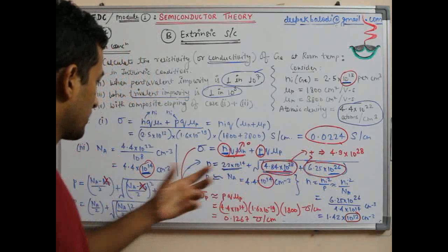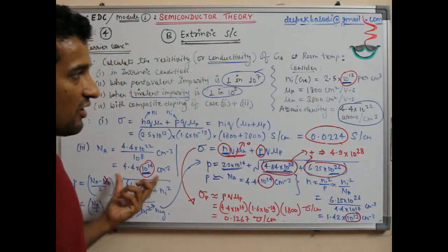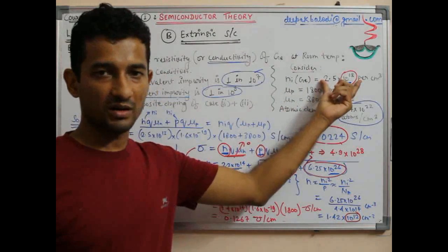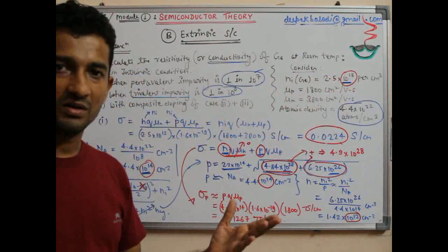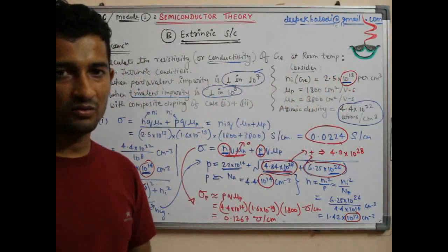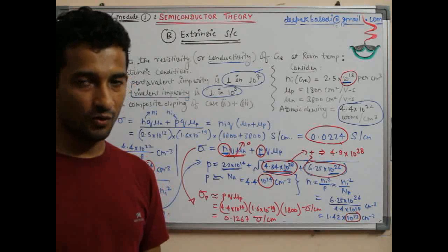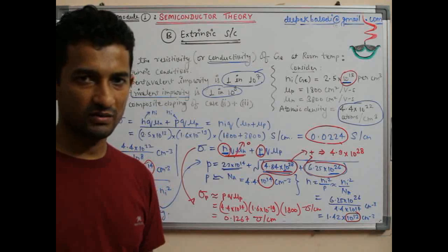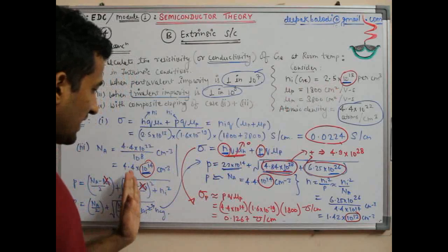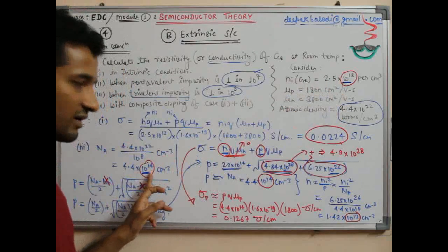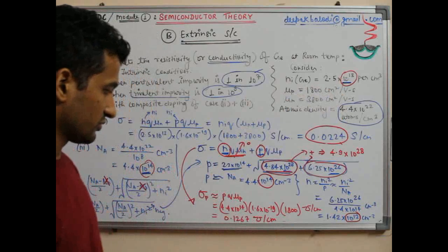So once we had doping of 10 to the power 14. Now you see this was not very impressive doping because already there is a carrier concentration of 10 to the power 13. So we only had a doping which is 1 order greater than that. So even 1 order is a much bigger amount than this, but still to achieve the benefits of doping, we should at least go for 2 or 3 orders more than the intrinsic concentration. So therefore we expected that because the doping is not far enough, the conductivity has also improved by 1 order. So it is this.